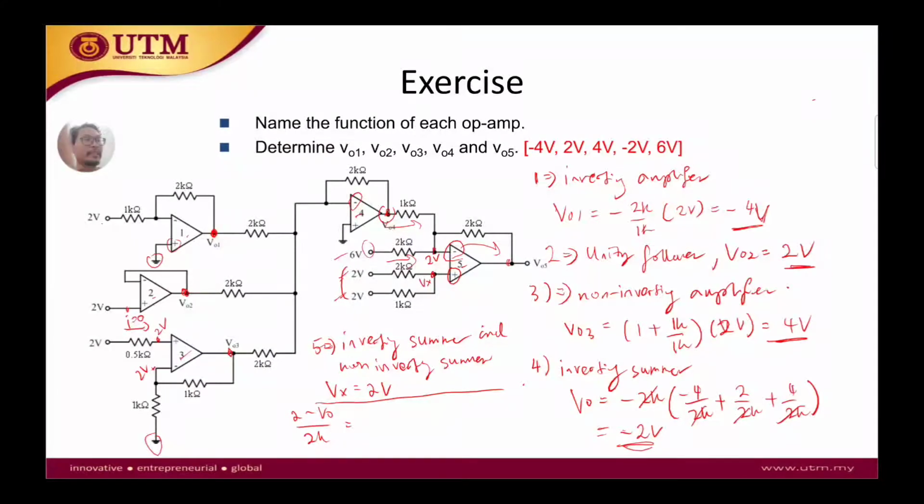So it's just going to be Vout4, which we calculated as -2. So it's -2 divided by 1K plus 6 minus 2 divided by 2K. The summation of this current and this current is going to be equal to the output current. If you do the analysis here, we have all the constant values, 1K, and try to take out Vout. If we are able to take out Vout, we can see that Vout is in fact going to be 6 volts, a combination of inverting and non-inverting.